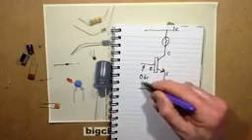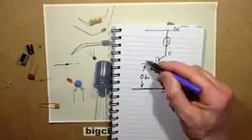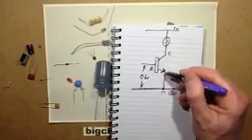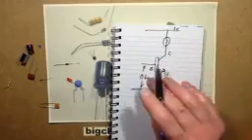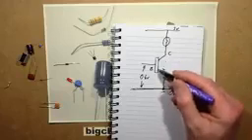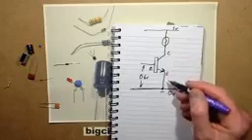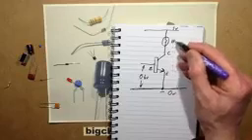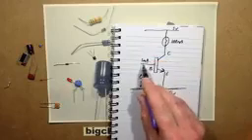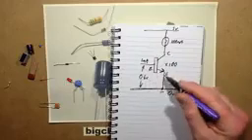it's silicon again, that's the standard sort of silicon junction voltage, above the ground rail here, the 0 volts, and a modest current, it will switch. A transistor typically has a value called a gain. It's got a voltage rating, a gain rating, a power dissipation rating. There are lots of other ratings, but let's keep it simple, because in most instances when you're using a transistor, it's going to be an NPN like this. So say you've got a gain of 100, and that lamp's going to pass 100 milliamps to light fully. Then you want to pass at least 1 milliamp into the base here, and that will be multiplied by the gain of the transistor, and it will switch the lamp.